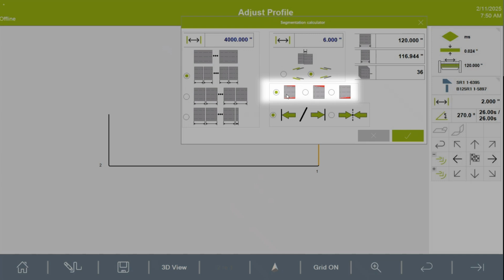When you're making a tapered part, you're going to be starting with rectangles where you have parallel sides. Okay, you're not going to be cutting a tapered blank. So when you start making these tapers, that part is going to skew itself and it's going to have excess. One end of it is going to be larger than the other, and we have to bury that excess somewhere. So you have three choices.